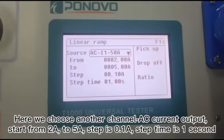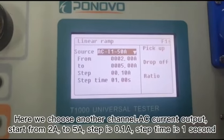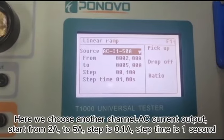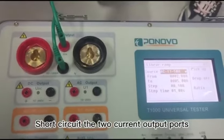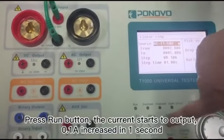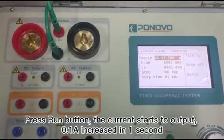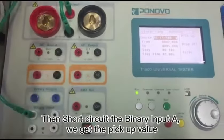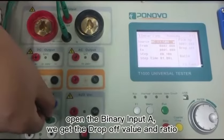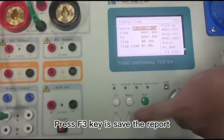Here we choose another channel AC current output, start from 2 amperes to 5 amperes, step is 0.1 ampere, step time is 1 second. Short circuit the 2 current output ports, press run button, the current starts to output, 0.1 ampere increased in 1 second, then short circuit the binary input A, we get the pickup value, open the binary input A, we get the drop off value and ratio. Press F3 key as save the report.